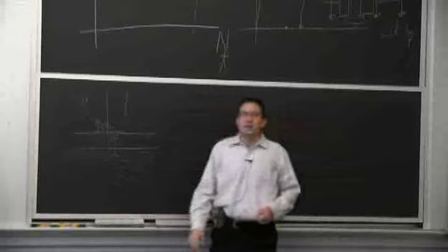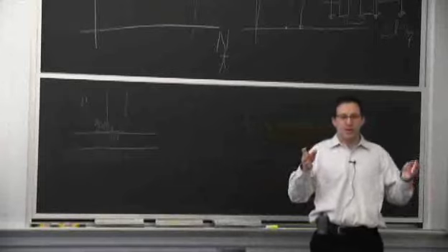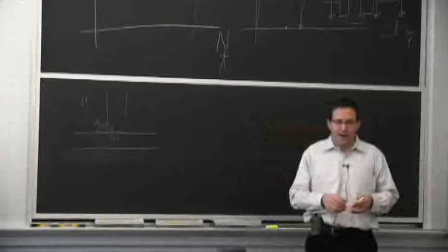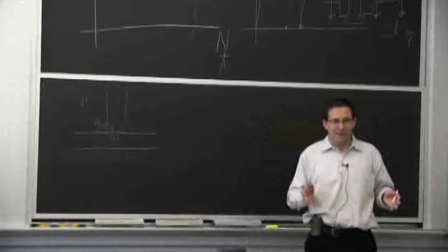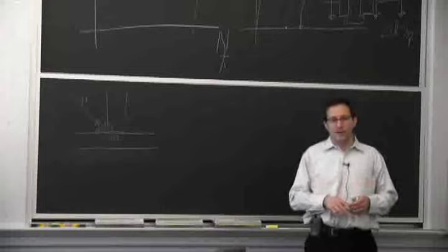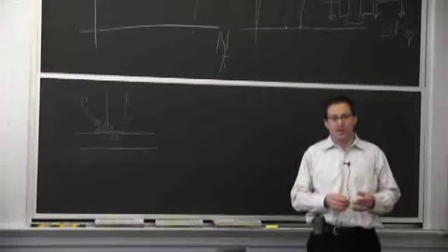Now, it's good and bad. You can think of it different ways because you reduce the yield strength. If you remember all our discussions about cracks, it means you're more ductile. So you can actually deform it more, everything else being equal, without breaking it.